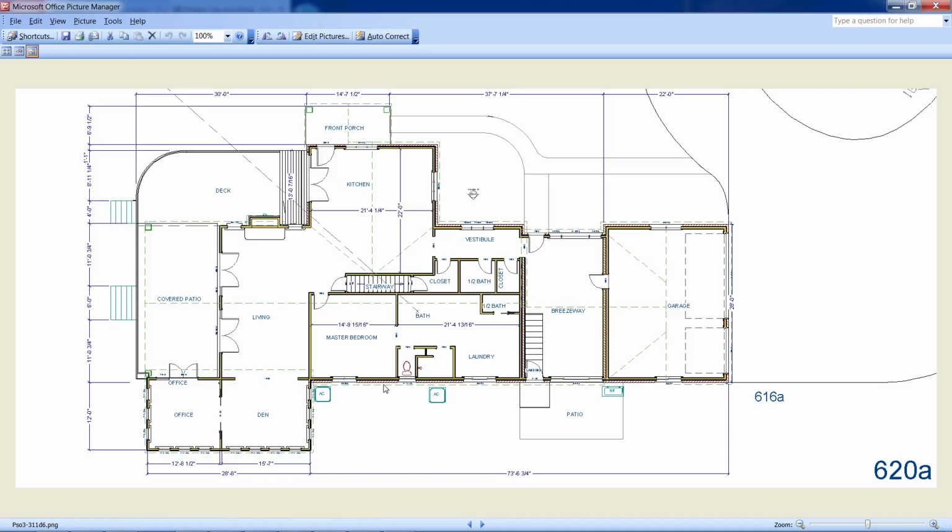But also with regard to that brick, I think I talked about this in the last film, these are both existing walls here, and whether those are taken down and reconstructed as all frame coming around here, or somehow modified where a portion of this is thin brick coming around here. But that will have to be firmed up eventually. For the moment, I'm showing it as just conventional masonry like yours, and then painted. It would just be concrete brick coming around this far here.